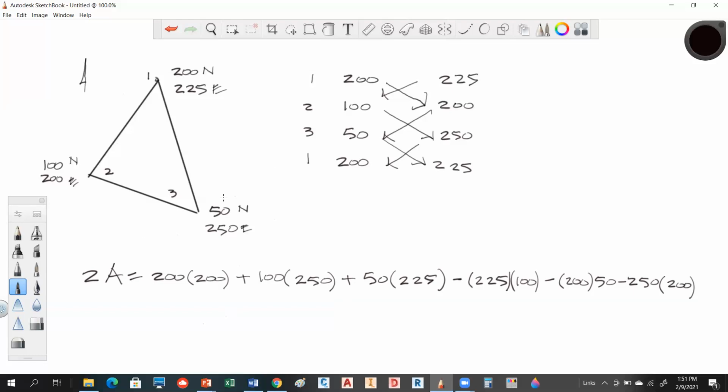So that's an area calculation by using coordinates. Otherwise, to do something like that triangle would be a little bit of a mess. That's not an easy triangle to solve if that's all you had. So you would be able to solve that pretty easily using that method. That's a pretty cool little trick to know, and he covers that in chapter 15.